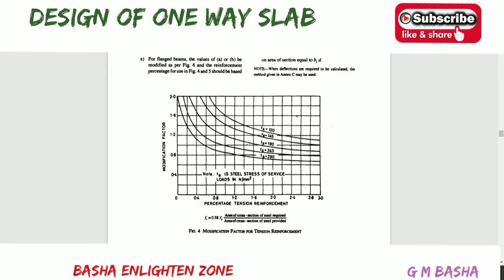So please relate these two. Here I told you this is 0.2, and in between 0.3 and 0.4 is 0.25, again in the middle. So relate to the 240 curve, and observe the value related to 240. The second curve is the 240 curve here. Keep a scale and you will get the value related to 0.245 reinforcement, and where it passes on the left side, that is the modification factor. For example, the curve is touching up to this point, so you can take it approximately. You won't get exact values like this in approximation graphs.